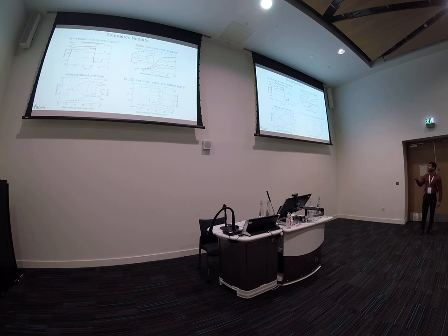Maybe I won't go into the details, but these are some simulation results. On the top left, you see a cycle power representation. In red is the mechanical reel-out power, and in blue is the electrical power, for rated wind speed, which is 16 meters per second. These are again the mechanical reel-out power and electrical power. The one in violet is the electrical cycle average, which we cap at 150 kilowatt, the required rated electrical power. But maybe we can come to these details later in the questions, if you have any.